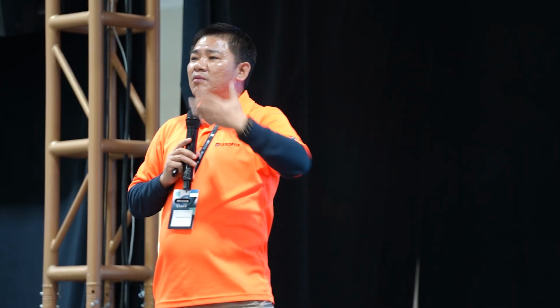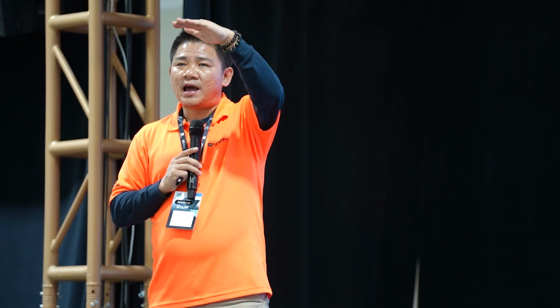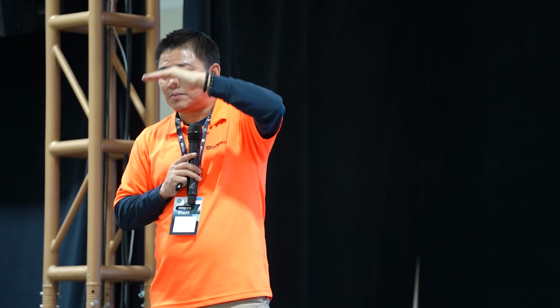So we are again smart people. We say, okay, let's go back to basics. Can I encode more bits per symbol? So you then start looking at higher modulation techniques. In NRZ, presence of light was 1, absence of light was 0, so I could only encode 1 bit per symbol. With PAM4, for example, pulse amplitude modulation level 4, I have 4 levels of amplitude, which means I can now encode 2 bits per symbol.